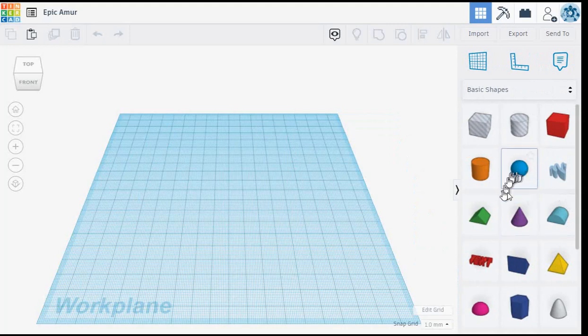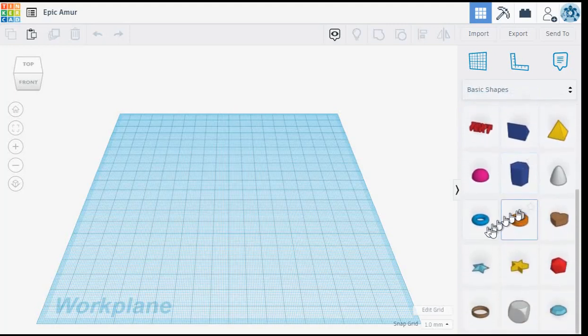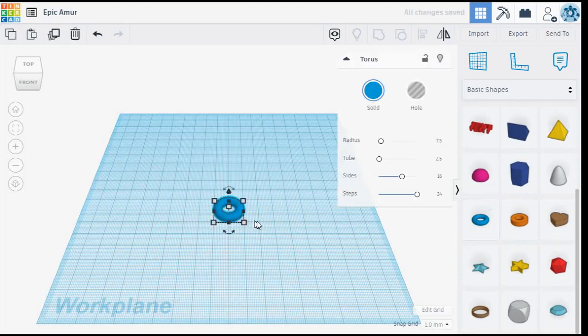In here we have various shapes that we can put together, including what I call negative shapes, which create a hole that's either square or cylinder. We'll use that for other shapes as well. To begin, we're going to use this pawn base. We'll click it once and move it out to the center. I like to line it up between these grid lines. So I've dropped it there.